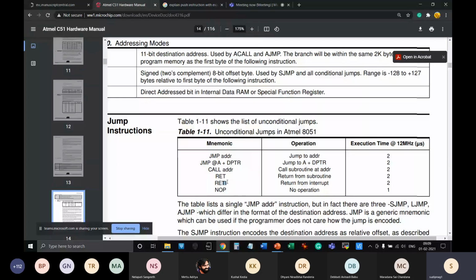We'll see in the interrupt registers, there are certain flags which actually get updated by RETI automatically, indicating that the interrupt has been serviced. That means you are done with the servicing of the interrupt routine. That is what is updated, which is not updated in a simple RET instruction. So this is the slight difference. It only updates certain bits. Apart from that, it also invokes two pop instructions for returning back to the original position in the code after the interrupt service routine.